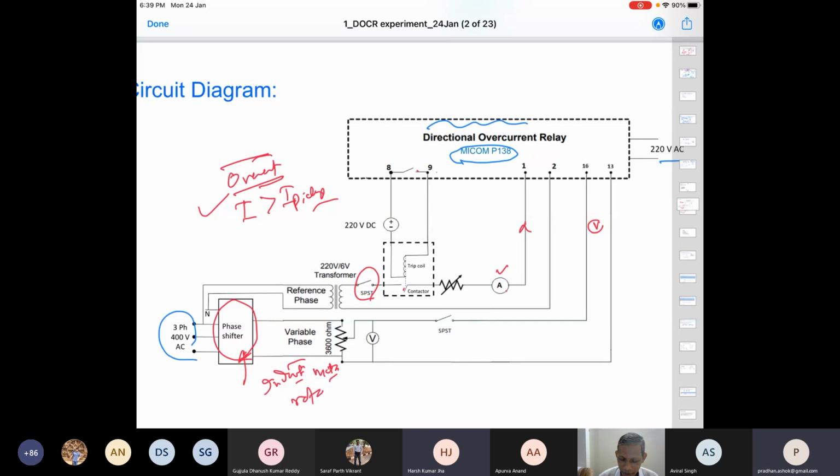If we rotate the rotor, giving the input to the stator slowly, the 3-phase winding in the rotor, slipping of course, makes different positions with respect to the stator winding, and gives us a phase displacement with respect to this input voltage, and that gives us the corresponding voltage varying with respect to this reference.